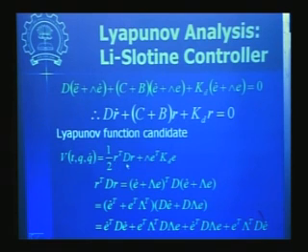So how do we do that? We have to first select a Lyapunov function. The choice of Lyapunov function will usually be energy based. Okay, in this case, since R is a new variable for error dynamics, we choose the Lyapunov function to be in terms of R. So this is not just dependent on error derivative, but also dependent on error.